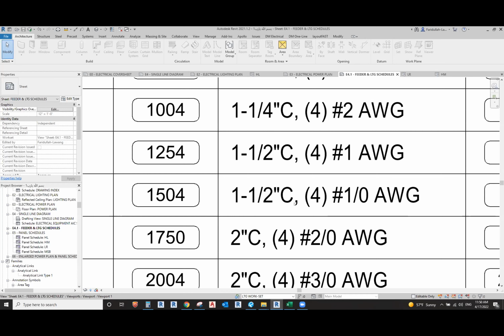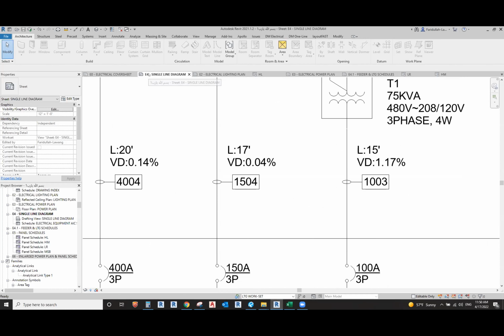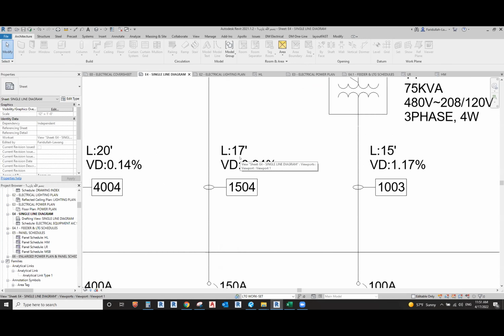So if you want to order it, you have to know what's the length. The company will ask you what's the length of this 1/0, or how much you order. So you go here in the E4 in this sheet, and you see that the length of that cable is 70 feet. This will affect your cost estimation. Suppose you have 100 feet, that will be more expensive, right? Compared to if you have 17 feet. How do you know that?